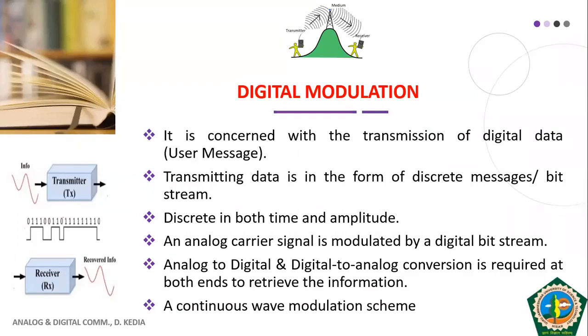But if you remember, when we defined modulation initially, when we started with this subject classes, I told you that we need a carrier. Though we said that the carrier in case of pulse modulation technique was in the form of pulses, it was not an analog carrier. So we can say that they cannot be fully called a modulation technique if we talk in terms of the carrier requirement. So that's why we have to move to digital modulation technique, where we will again be using a sinusoidal carrier, which will be of high frequency in nature.